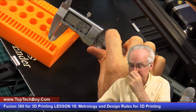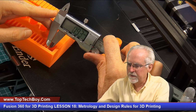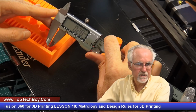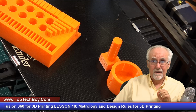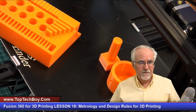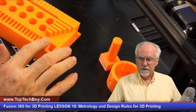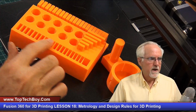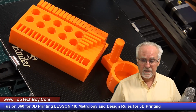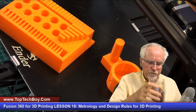And then we're going to come down to this amazing 0.2 millimeters. We wanted 0.2 millimeters, and we got 0.24. And so again, we're printing to 0.2 millimeters to within 0.05 millimeters. So that is really pretty amazing. Hopefully it makes sense what we're doing. We're just looking at our precision as a function of line width. And you can see that for different line widths, our precision is staying at 0.05 millimeters or better.